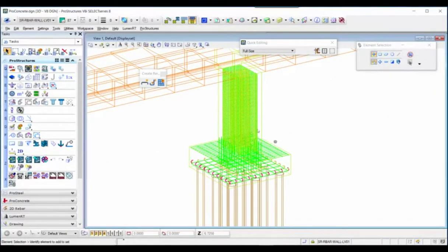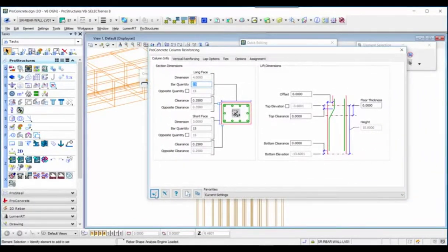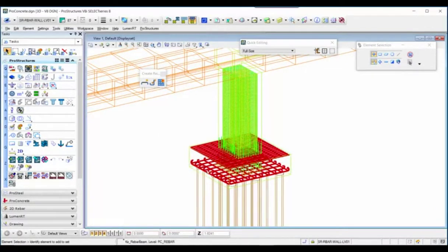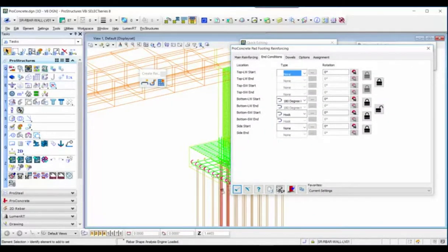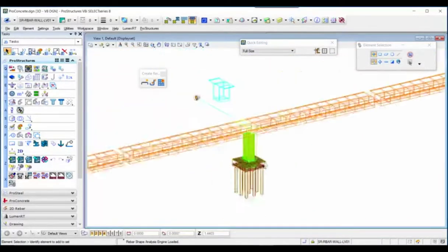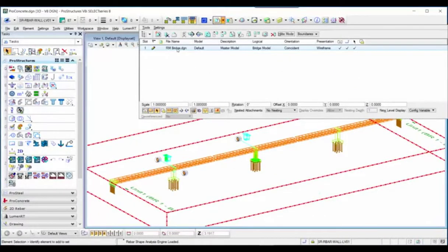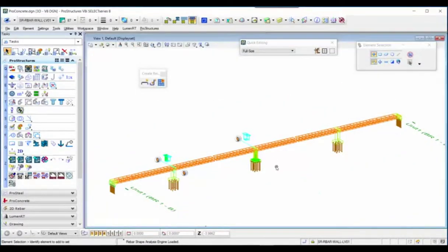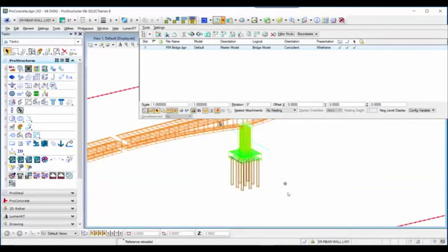So what you see here is the original model, the one that is straight. I have some reinforcement in there already, as you can see here, and then what I'm doing is taking this model and reinforcing it. Since it's a reference file, I want to simply reload the model that I have modified from a straight alignment to a curve alignment. And guess what happened to the pier that I have there with reinforcement? It will be updated, relocated, forced to follow the new changes.